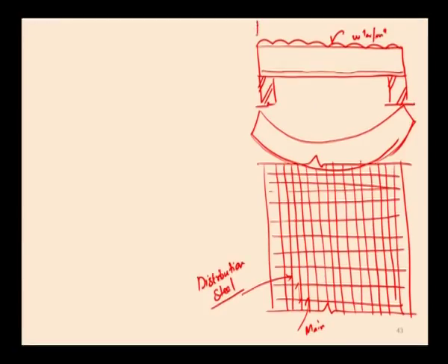Now, the second case. This is a simply supported slab. I am telling you an example of a pure simply supported slab. There is a slab which is provided over the septic tank or the water tank constructed in a residential building, that is freely resting on the wall. That is an example of a pure simply supported slab. Other than this, there is no pure simply supported slab in the construction of buildings, understand.